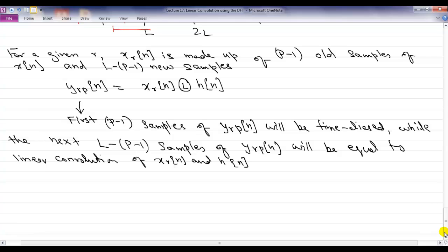Okay, so mathematically, what I want to do is keep y_r[n] equal to y_rP[n] for P minus 1 less than or equal to n less than or equal to L minus 1, and 0 otherwise. And then I output all of that.